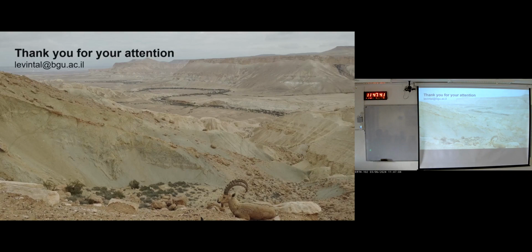And then we said, okay, I know there are algorithms to lower the drift. So we read about that algorithm, and then we said, okay, let's put three sensors, still low cost, of the same parameter, CO2, one next to each other. And it's still low cost because it's $150 per measuring point. It's still 10% of what we usually buy for a commercial sensor. And these sensors are now at the same depth, measuring the same parameter, but the algorithm is always comparing between the three.